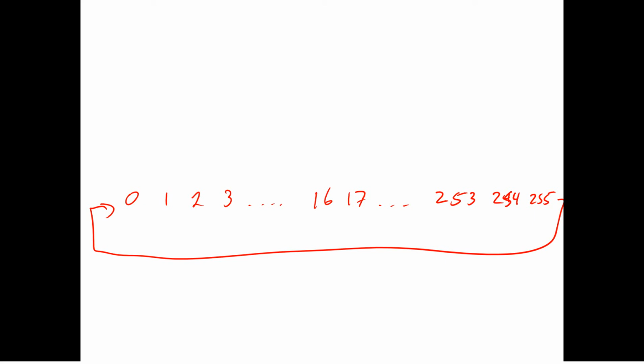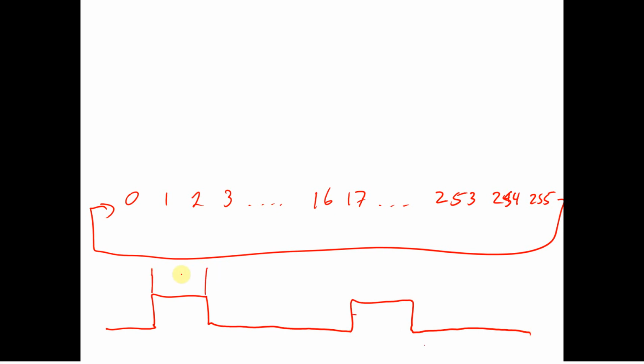For the pulse width modulation, if you remember it from the lab, what we want is some delay in here. So we have a repeating sequence, but it's only on for, say, 20% of the time, and then it's off 80% of the time. So this would be a 20% duty cycle. How we can use a timer to give us this is we take that external pin, and I'm going to program a value where it goes high, say 3, and another value where it goes low, say 17.